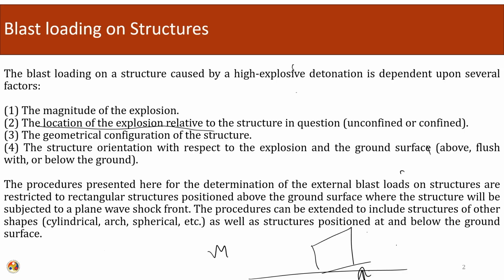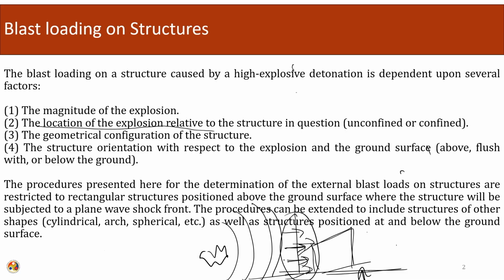It means that if the blast loading is occurring like this, what the structure sees at the end of the day is a planar front. Okay. The blast normally occurs in this fashion, but when it hits the structure, we are assuming that it forms a planar wave front. Okay. So, this is our assumption. The structure is above ground and the effect of the blast that the structure is seeing is a planar wave shock front.